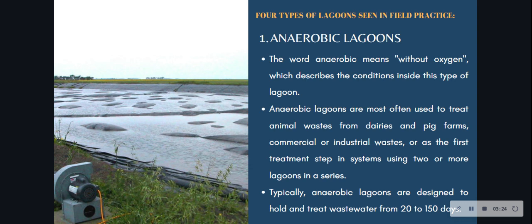The wastewater that leaves an anaerobic lagoon will require further treatment. Odor can be a problem with anaerobic lagoons. However, in many cases, odor can be managed through a variety of methods such as adding sodium nitrate, recirculating pond effluent, and through regular maintenance.